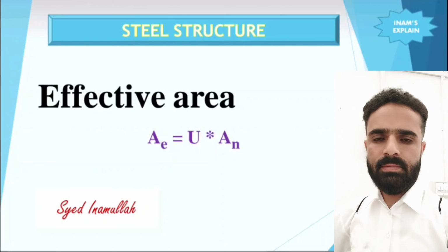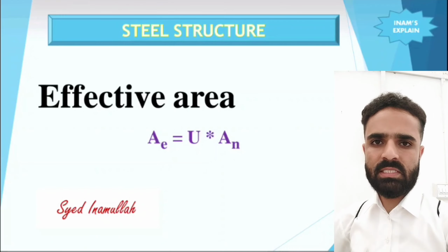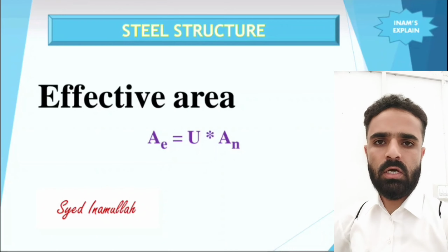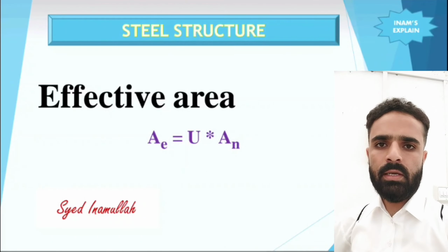Have you ever thought why the effective area is not equal to the net area in a tension member with holes? The answer lies in shear lag. This lecture will explore the concept of effective area, a powerful tool that goes beyond simple area reduction to account for shear lag and ensure safe and efficient tension member design.